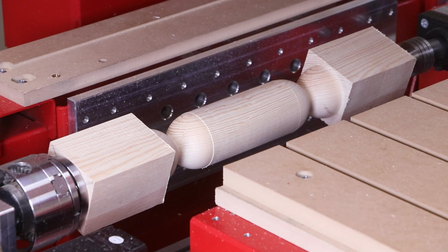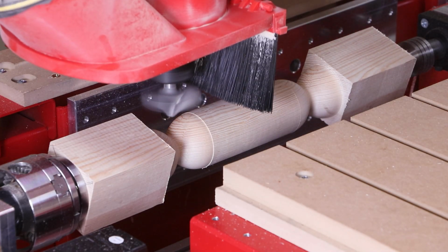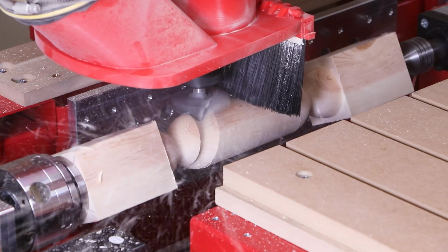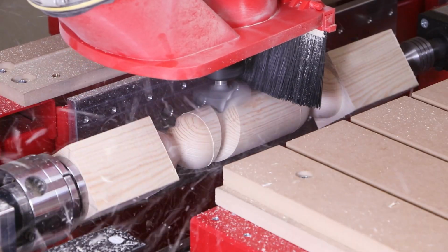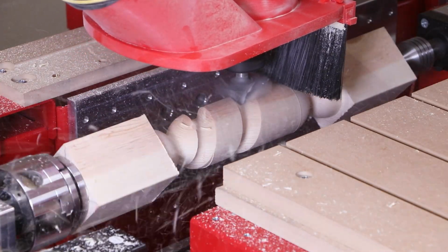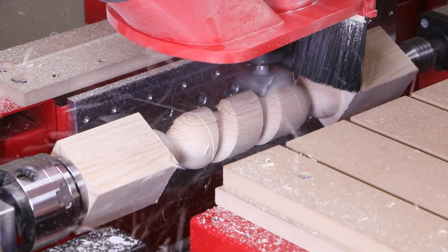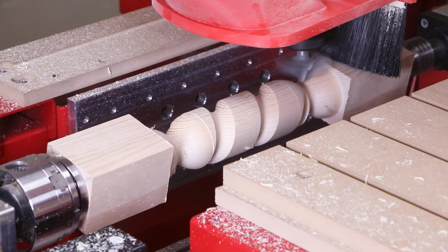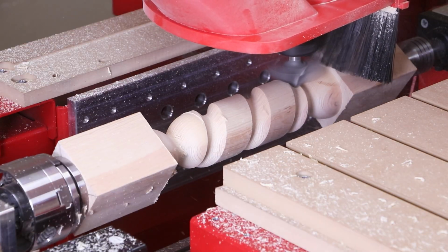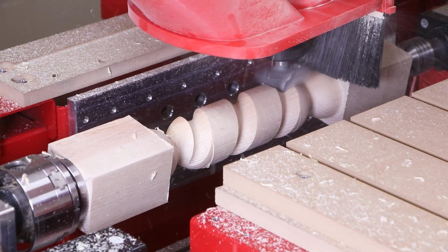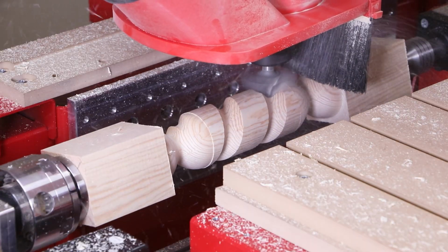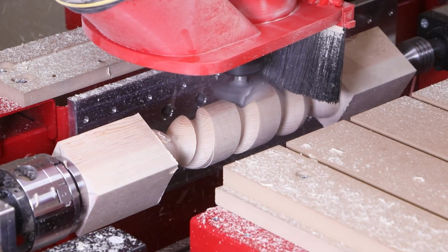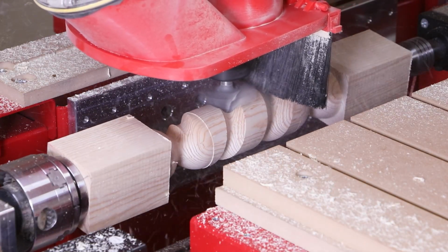So just like we programmed, the cutter starts at the starting position in this tool profile, plunges to the first depth and then travels down the stock while continually rotating the material. Now remember, we had also told it to do a single start, so the cutter is actually traveling the width of the cutter, which is 2.5 inches down the x-axis per one full rotation of the material. It will repeat this by plunging a little further and coming back. This barley twist process is going to take 4 cut depths in total to give us the final detail.